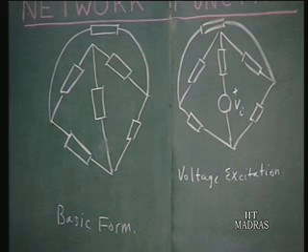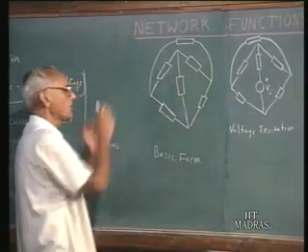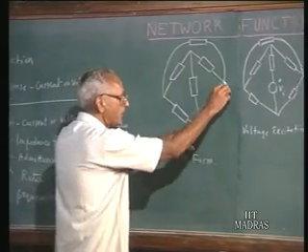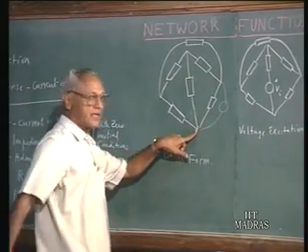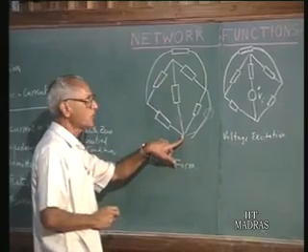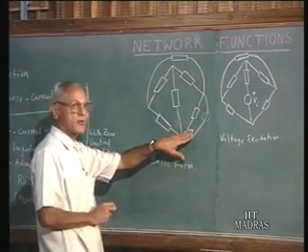So when you introduce a voltage excitation, you must make sure that if the voltage is made equal to 0, that means this is short circuited, the original form of the network is obtained. If you had put a voltage source here, then the voltage is reduced to 0, this is short circuited. Therefore, the original network is modified, it is not the same network as before.